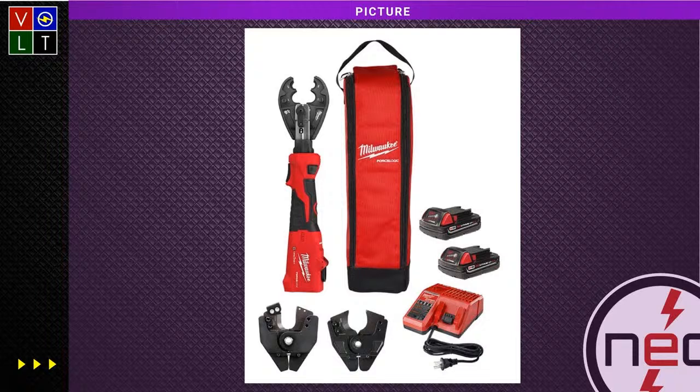You don't want to use the wrong die. So when you're crimping those conductors, you have to look at the actual crimp sleeve that you're using, the wire range that it is, and then make sure that you have the correct die that goes in there. When it crimps, it'll leave an imprint, and that's what the inspector checks when he looks at it and says, oh, okay, cool, you're using 250 MCM, and the 250 MCM range is listed on that imprint that the crimper leaves. Then he's going to sign you off, and then you just heat shrink it, land it, good to go. So definitely an awesome tool.